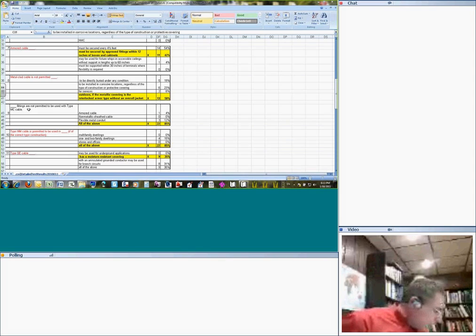In 2008, they changed it and they allow you to do it. It says exposed to any of the destructive corrosive conditions A or B unless the metallic sheath or the armor of the cable is resistant to the condition or is protected by material resistant to the condition. So this unless. I can see your point.